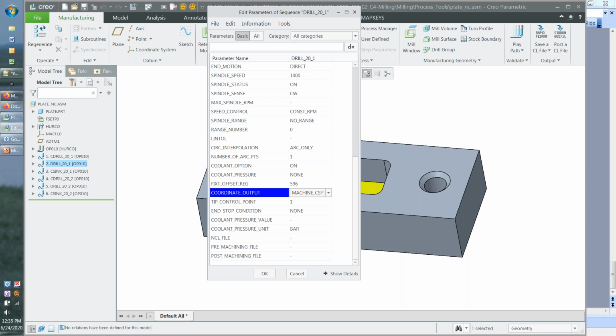You are obviously able to do the very same thing and handle dynamic offsets in that way yourself to handle whatever outputs you want. The thing is, a lot of people get hung up on typing in all this extended stuff here. That's not where it goes. You get to put in whole integers in the fixture offset register. You get to handle whatever you want to do with that integer in FIL. And this is how we do it. That's how extended or decimal offsets and those types of things are done. We just extend the number. You don't type in G59.6. You don't type in G anything. You just type in 596.